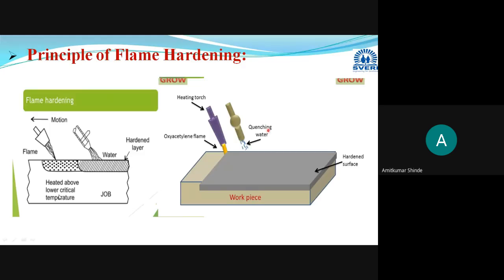Here one mistake is there in this diagram. Okay, I will explain it. Instead of lower critical temperature, you have to heat it above upper critical temperature. Okay, this is above upper critical temperature. This is not lower critical temperature. Upper critical temperature should be there.